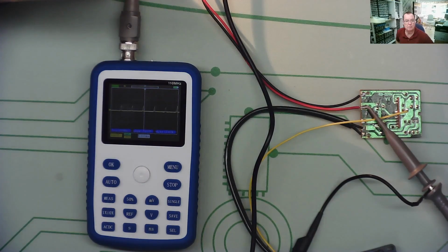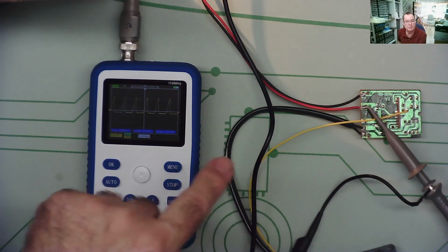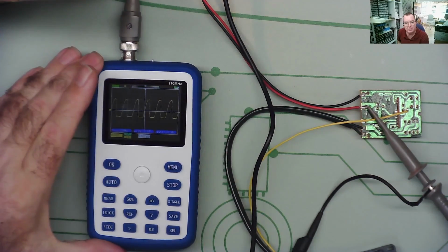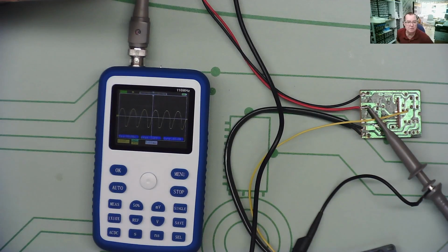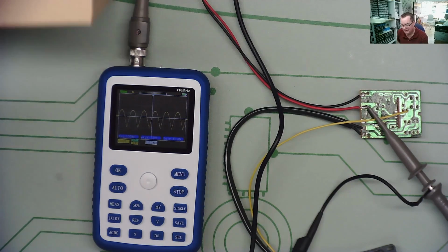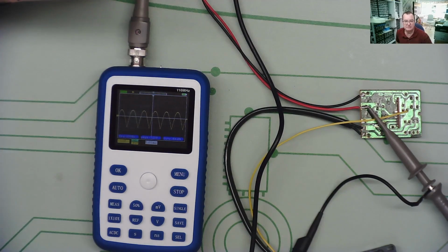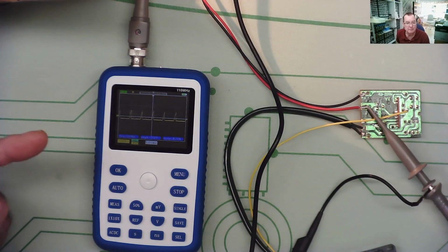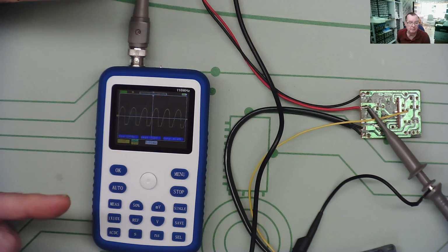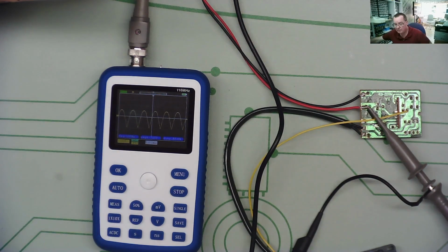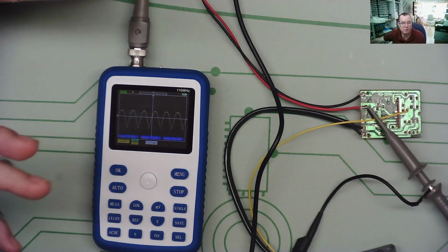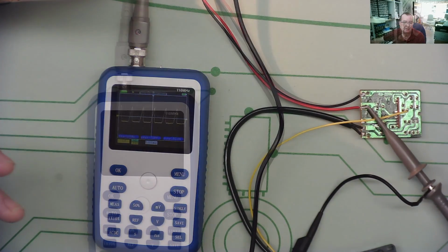Okay, I've now attached the scope probe to the signal, which is effectively going directly to the light bulb. You can see there, so it's now going to full brightness and then off again. That's what you're actually having. It's going through the various brightnesses. It's now, if you like, doing the other bulb, the one I haven't got connected. This one's driving again, yeah? So you can see. Okay? So that's basically the sort of waveforms you'll find on a thyristor.